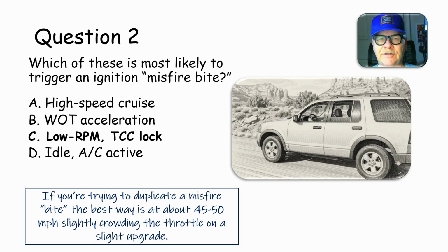Back in those days I had that big Sun Interrogator sitting in front of my service bay, if you know what that is. The car ran really smooth, really good, but I went ahead and put new plugs in it, and points and a condenser, and set the points like they were supposed to be, set the dwell and all. I even had a dwell meter in those days. The guy took it and drove it and said, I'm still having the same problem.